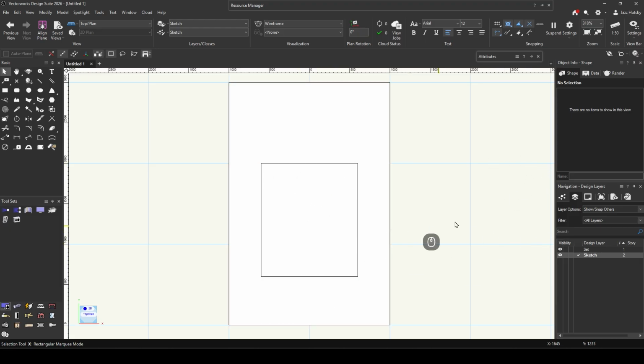Now I want to create the circle. Now this is going to be easy, thankfully. If I go to my circle tool here, and again, checking my tool options at the top here, I want to be in radius mode. Radius mode means that the first click will define the center of the circle, and the next click will define the outside of the circle.